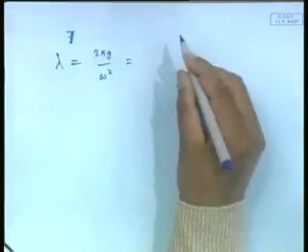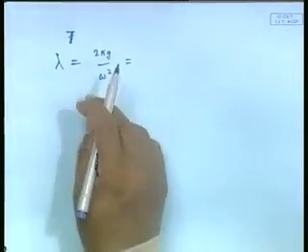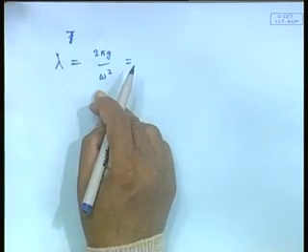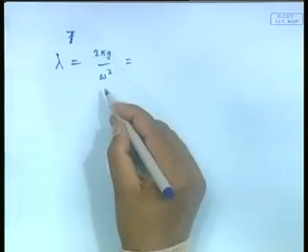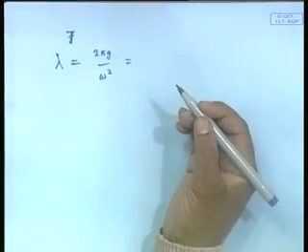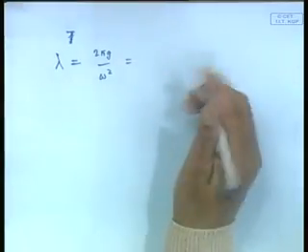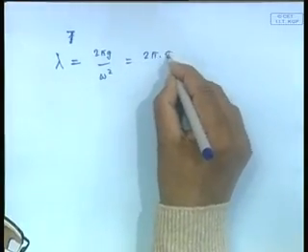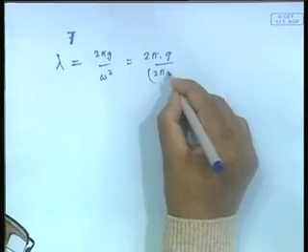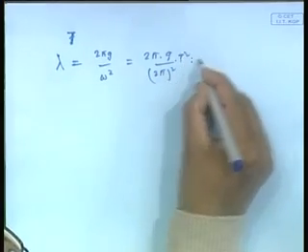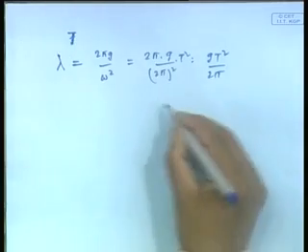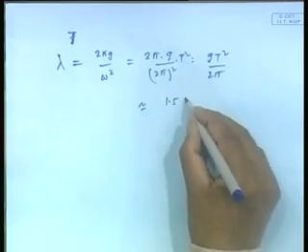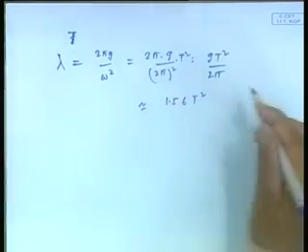So, because we are trying to relate this now, if you were to put in SI units, lambda is in meters, g is in meters per second squared, and period T is in seconds. Actually, I can write this as g by 2 pi squared by T squared. So, this turns out to be gT squared by 2 pi. So, this becomes almost 1.56 T squared in SI units.